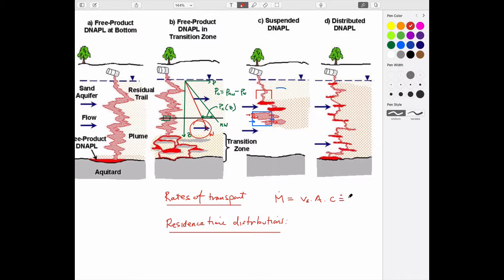Darcy's velocity comes from Darcy's law, so V_D is equal to K over mu, relative permeability, and the pressure gradient, kind of, right? If you can see that.